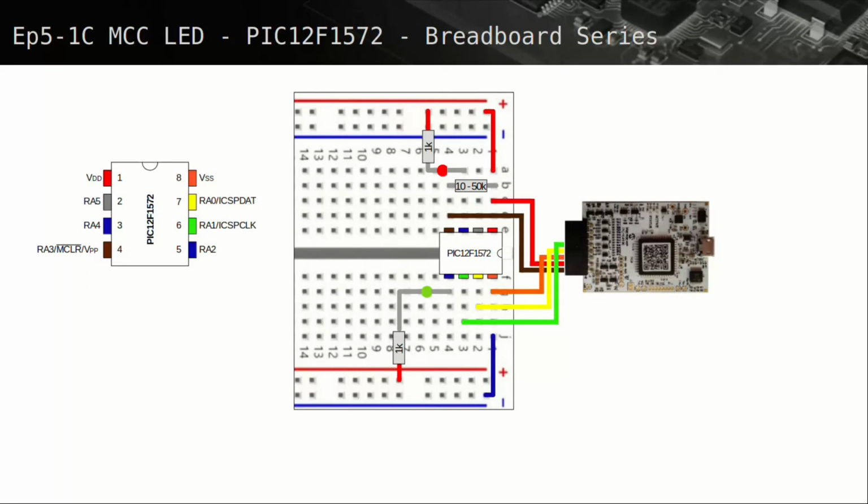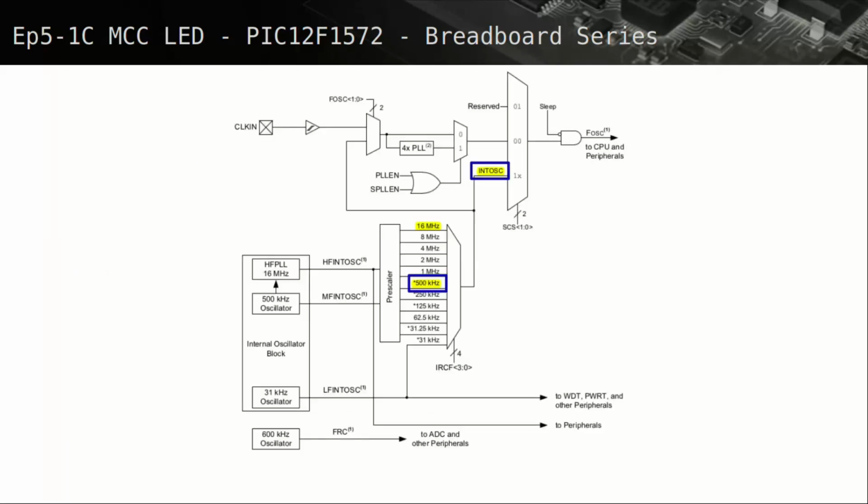The LED being toggled on and off will also be covered, as in the previous register programming tutorial, using the default 500 kHz oscillator setup, and then modified to run at 16 MHz after a reset. This is done using MCC and directly edited in previously generated MCC files.